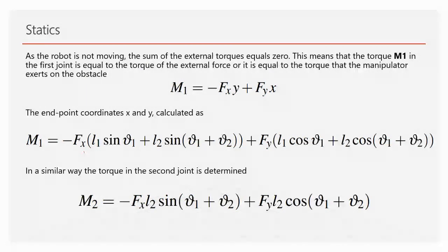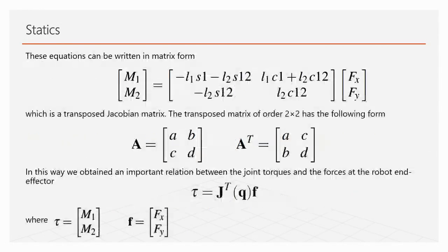we need at M2. And again, writing that in terms of matrices gives me a relationship with the famous Jacobian matrix again. The Jacobian matrix comes in again, but in transposed form. In transposed form, here is the relationship between force and torque. How much force I need, how much torque I have to apply, how much torque I want, how much force I want. We want this, then it means we need this at our motor.